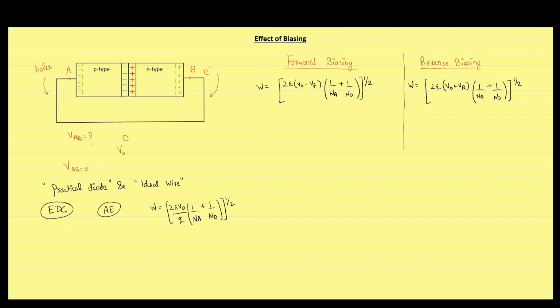And the formula which we have is of maximum electric field, which is given by. This expression can actually be written as minus 2V0 divided by depletion width. This formula I have already derived, and this is just a rearrangement. If we first put the value of Xp in terms of doping concentration and acceptor concentration, and after rearranging the equation in terms of depletion width, you will get this expression.